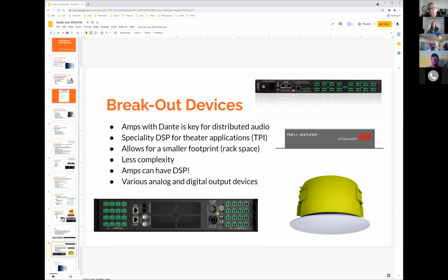Pretty wild. So in an area where you may just have network connectivity, we can inject, obviously it needs PoE, but we can get audio playback in a room. Obviously not tons of power, 8 watts. So it's not going to drive big speakers or anything, but it's enough to get proper background music in most applications. Very popular in marine because you can put this in cabins or staterooms or something, or obviously smaller spaces where you don't need that amount of power.